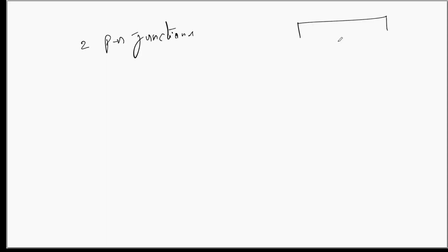If you look at the structure of a transistor, say this is the collector, this is the base, the thinnest region, and this is the emitter. If you consider this to be a PNP transistor, then we have a junction here. The first junction is between the p-type semiconductor and n-type semiconductor. Similarly, there is another junction between n-type semiconductor and a p-type semiconductor in a PNP transistor. A similar thing also holds good for an NPN transistor. Since we have two PN junctions, there are four different ways to bias the transistor.